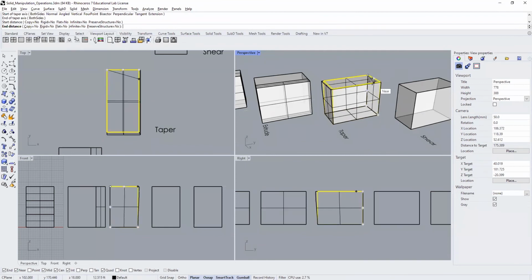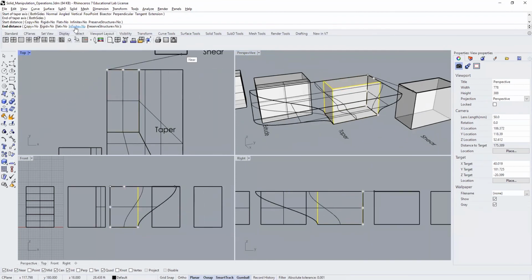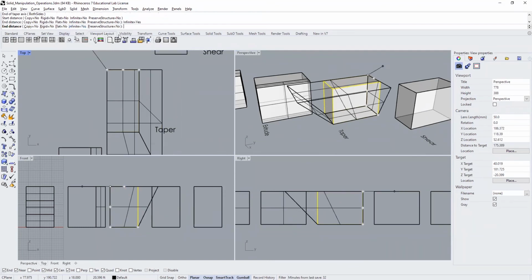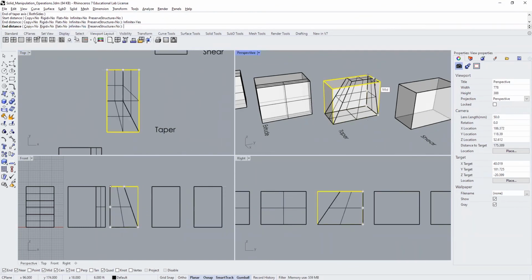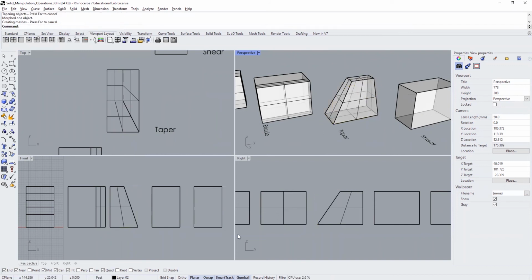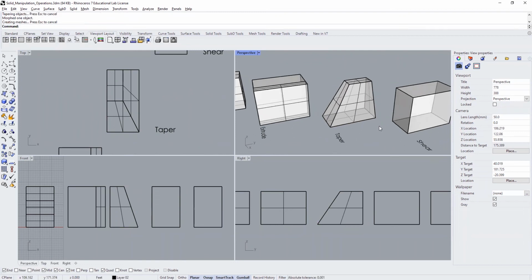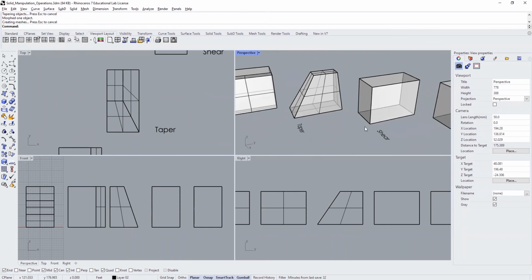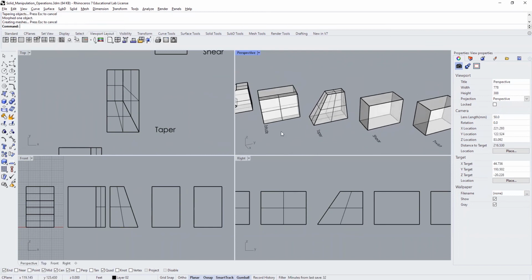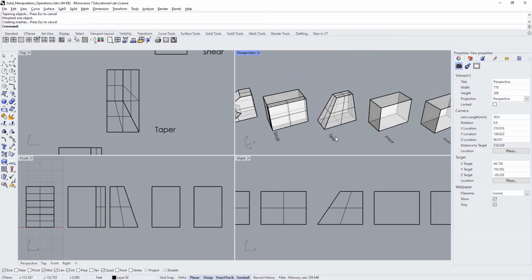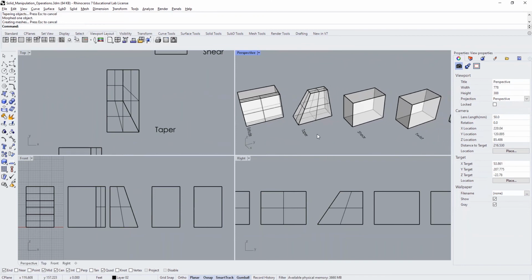If you want it to be straight, you would select the infinite tool. And as you can see, it's generating straight lines there. I'll just go ahead and click on the midpoint. I'm also going to turn off the nearest object snap. You may or may not need to do that, but you'll see if it's producing the forms in the following portions of the tutorial to make that determination, or just turn it off.